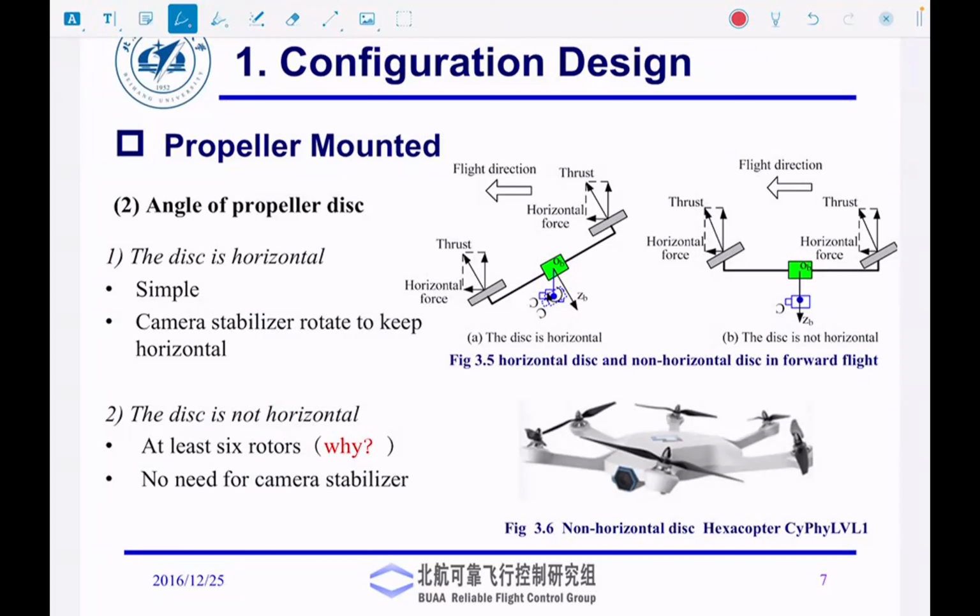Okay, once again, initially the problem was, if you have the quadcopter with vertical props, vertical motors, it cannot go like this. If it has to go left, it needs to tilt and go. If it needs to go forward, it needs to tilt and go. With this, here you have a component of thrust in the X and Y direction. So you overcome that underactuation by this.